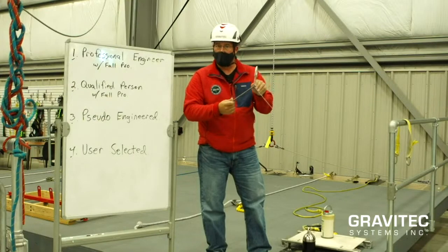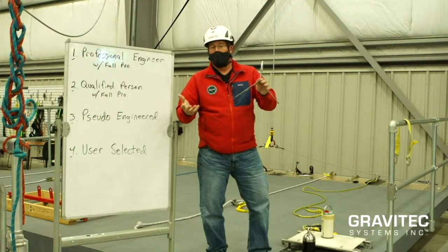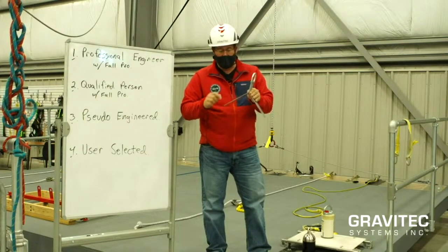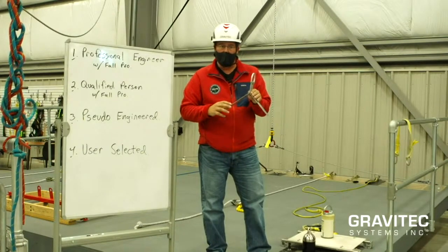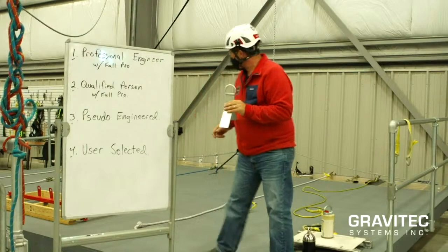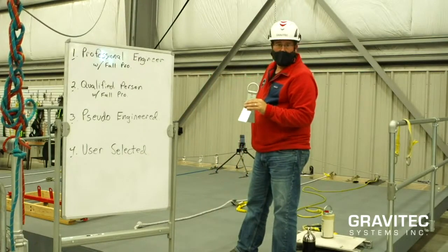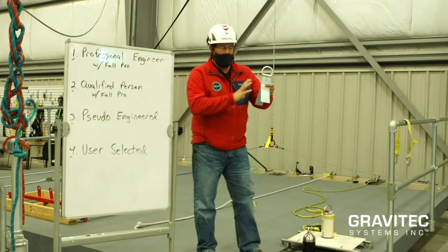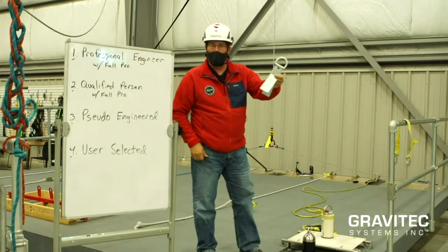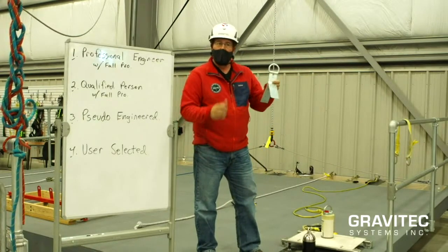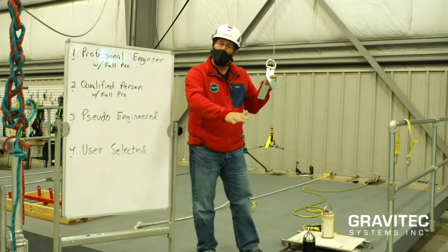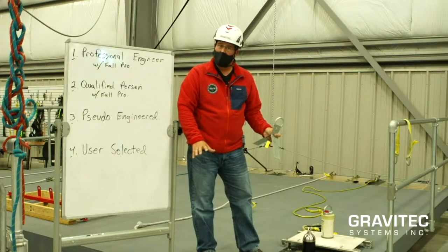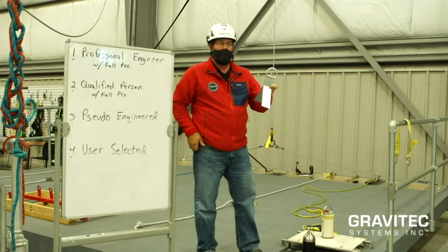They nail down onto the residential roof. Actually, not even residential. Anything that's got a peak similar to a house. And they just nail down or lag screw according to the building materials. Here at our training center, we've got 15, 20 of them back here on our roof section. So the anchorage connector is this part, the actual D-ring and plate. The anchorage is going to be the sheeting, truss, framing, wall forms, foundation of the house. Okay, so essentially you're connecting the entire house.